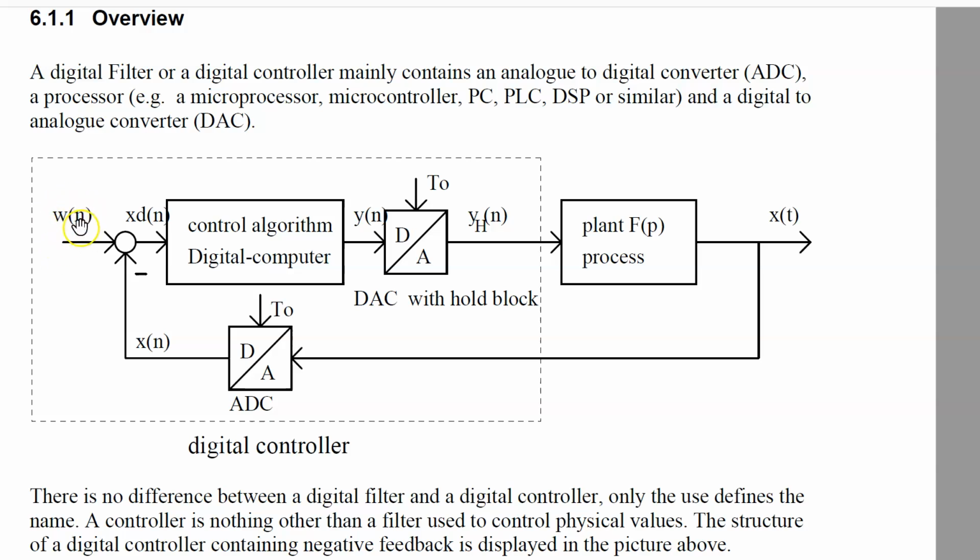Here you see a single loop system needs a set value, a reference value. This could be an analog one, but mostly this is a digital value, because then you can control the desired value with the computer, have nice human interfaces to set the desired value. The difference between measured output of the process and the desired value gives the control error, the control difference.